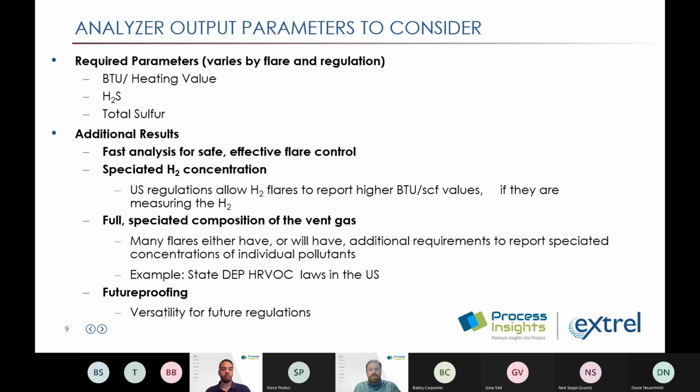This is not an energetic molecule, but it is extremely combustible. And so if somebody owned a high hydrogen flare and the concentration of hydrogen went really high, it was going to put them right against that limit for being out of compliance. But they were still going to have a really combustible stream.